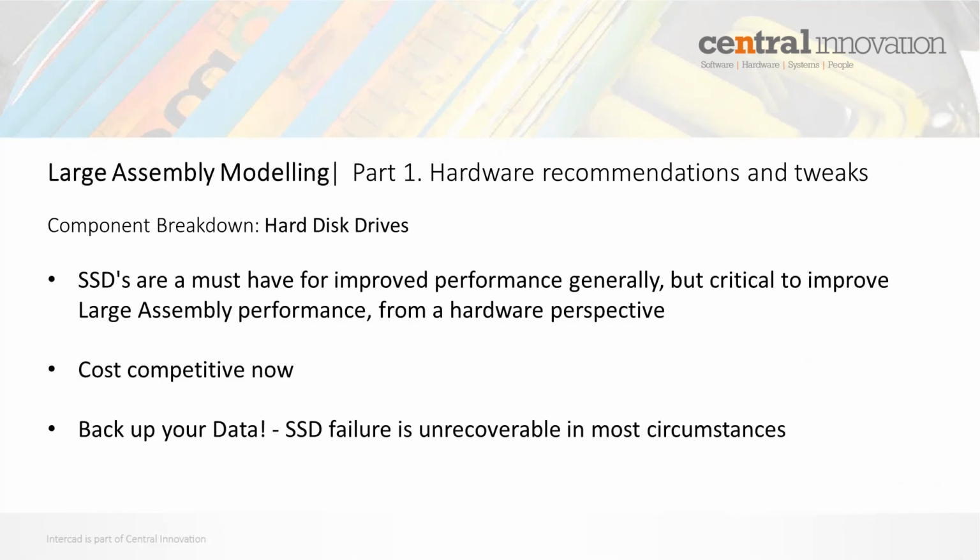So in terms of hard disk drives, SSDs are a must-have for improved performance generally, but critical to improve large assembly performance from a hardware perspective. SSDs are cost competitive now, so if you compare using this as a C drive compared to a large mechanical drive, you probably only need about 250 gigs to get your operating system and your program files on there, so I'd say that they are well and truly in the ballpark